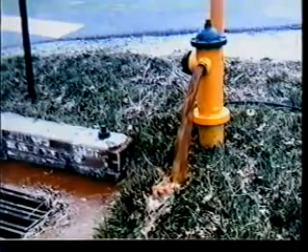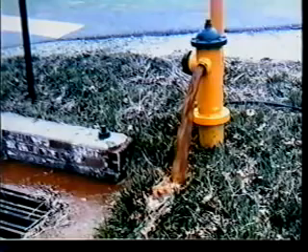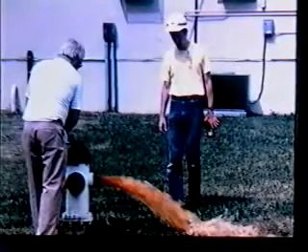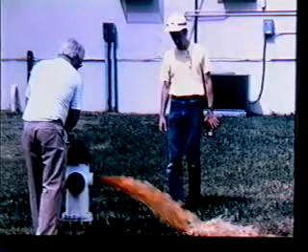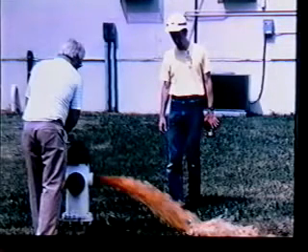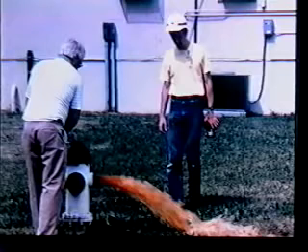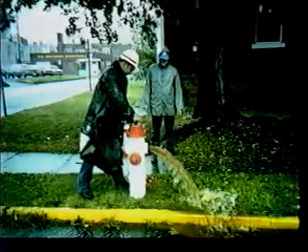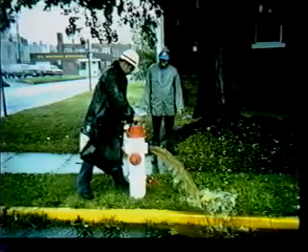You also need to be conscious of the fact that a hydrant flow test tends to stir up any rust or sediment that might be lying in the bottom of the pipes, and this deteriorates water quality. If there are people out there who will be affected by this change in water quality, such as laundries or hospitals, it's worthwhile to notify them about what you're going to be doing and when you're going to be doing it, so that they can take steps to minimize the impact of your test on their operation. It's just good public relations to let people know what's happening rather than surprising them with poor quality water.